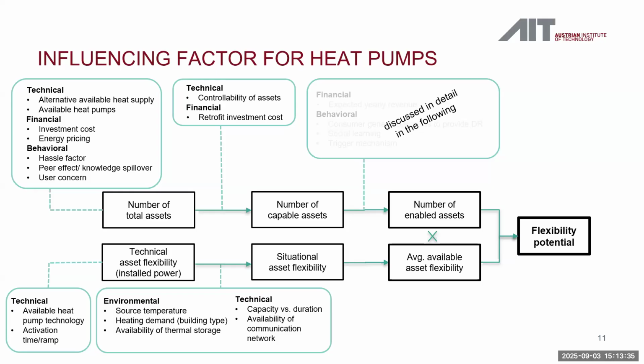Then there is the heating demand, also dependent on the building type, but also on behavioral factors. And is there storage available, which also means you can only switch on a heat pump if you can load a storage or supply the heat demand that you currently have, or maybe preheat your building. On the other hand, you can only switch it off if it's currently running and currently supplying heat demand or filling up a storage. Technical factors would be capacity and duration, which are not independent of each other.